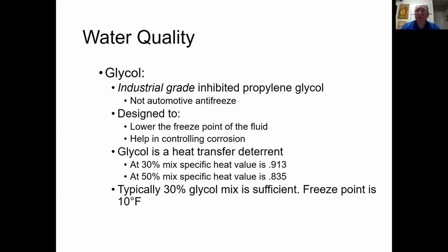Through the evaporation process in the tower, if you put glycol in the system and that water evaporates, you're just going to have a sludgy mess in your tower and in your wet decking and in your tank, and it's not going to be a good thing. So don't put glycol in your tower system.